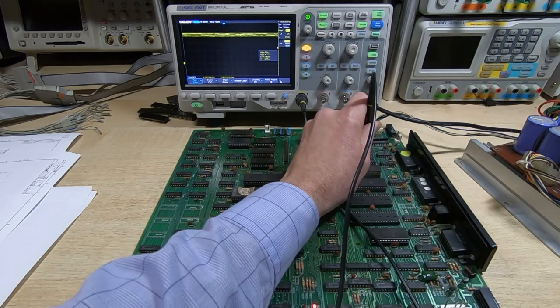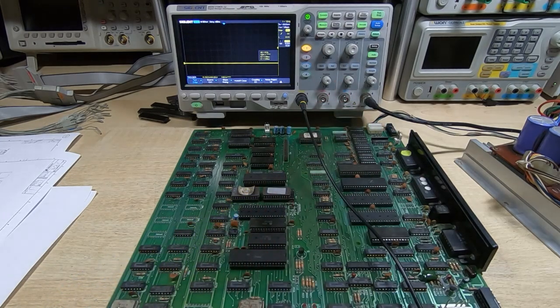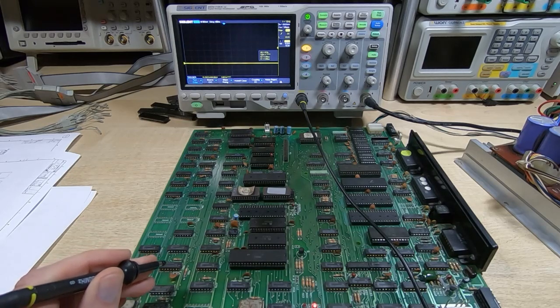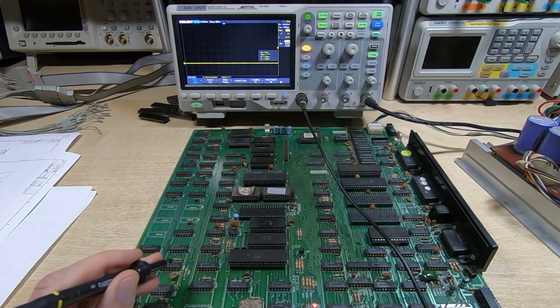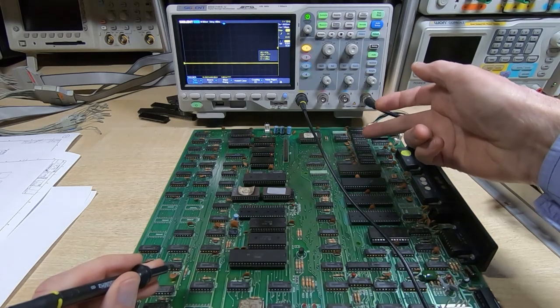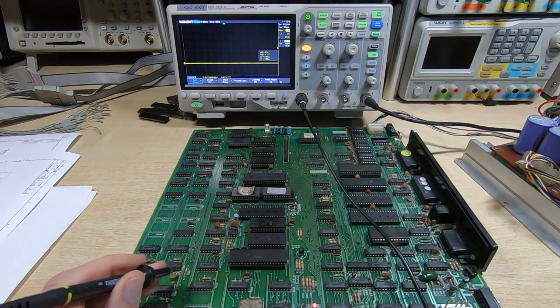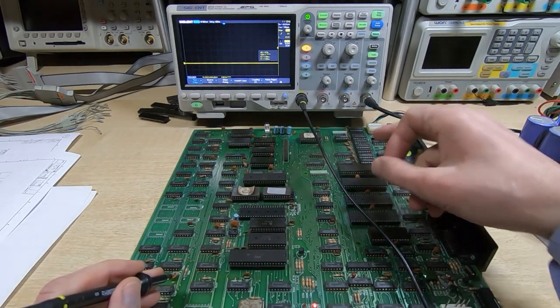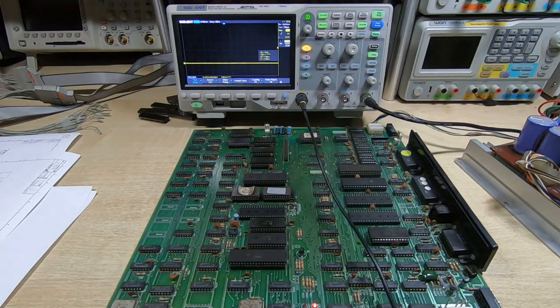I'm resetting the board because, as we saw, it's only reading 100 bytes, or writing 100 bytes and then trying to read it back. So we're only going to get a quick burst of CAS signals. The RAS will be there all the time because that's part of the refresh cycle, but clearly there's nothing coming through to the DRAM in terms of the column address strobes.